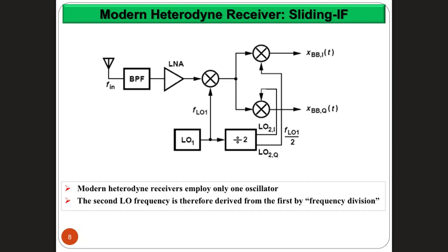Many issues, first of all, they can easily become out of sync from each other in terms of phase. So you can encounter some phase shifts between one oscillator and the other, which is a very common problem. In addition to that, oscillators are typically high frequency components with something called phase noise and frequency jitter. So they have some frequency variations. They cannot really be stable. It's not really a single frequency. It's a frequency that drifts a little bit with an allowable percentage. Now, if a drift happens in one stage, you want the drift to be the same in all other stages. If they are separate oscillators, this is almost impossible.